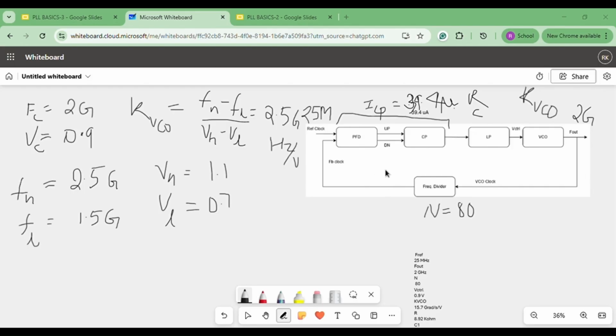Our PLL works basically in the frequency and phase domain, but actually in Cadence we don't have that to utilize. So what we have modeled here is: for frequency we are taking current sources, and for phase we are modeling it as a voltage source. So the first block is PFD, so we have used a voltage controlled voltage source to model PFD.